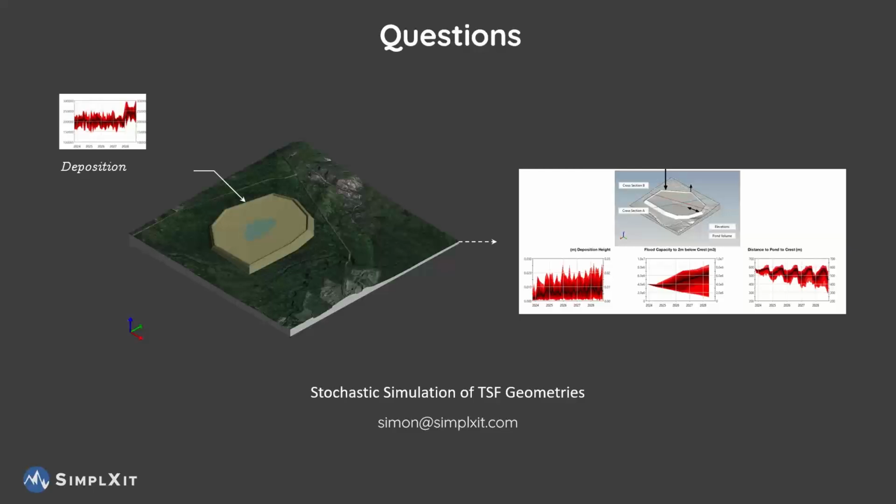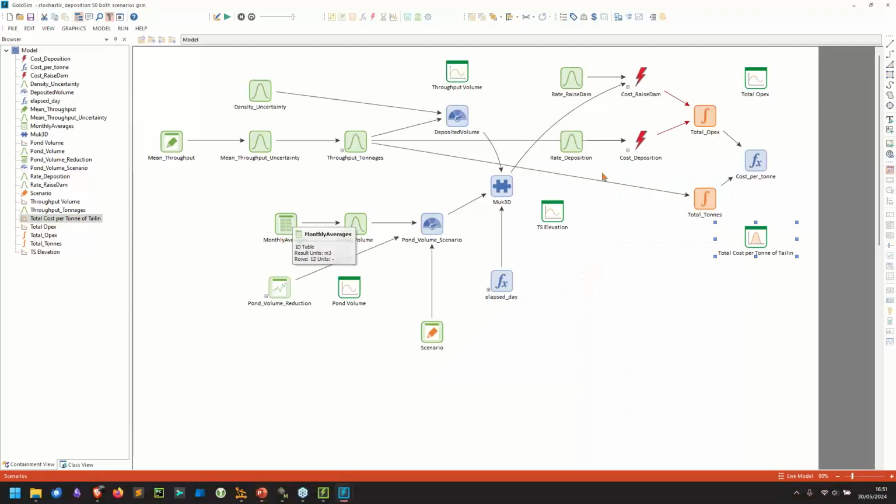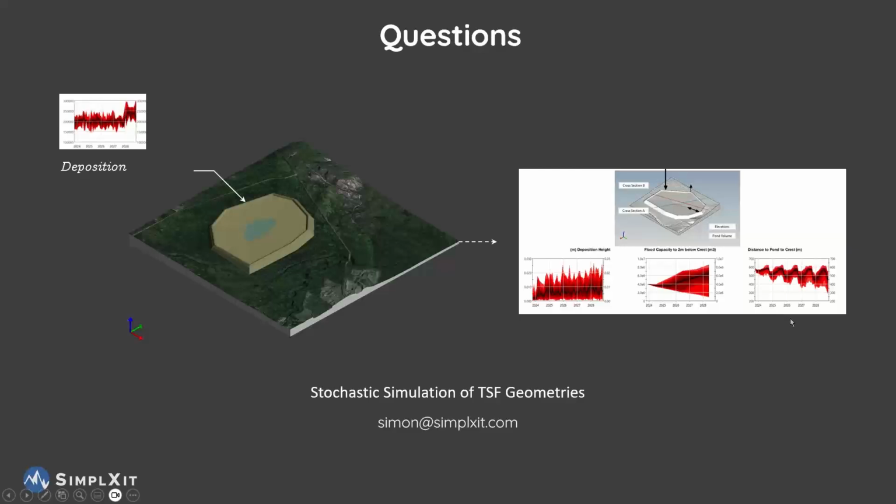In this model, I use the model from eWater, the Australian eWater, to fit a distribution, and ultimately I've got a time series which has 2,000 years of rainfall. And I just changed the, what is it called again in GoldSim? Time series shift, to shift annually in between each of those years that have been simulated outside of GoldSim. So it's not actually a stochastic model within GoldSim, it's external.